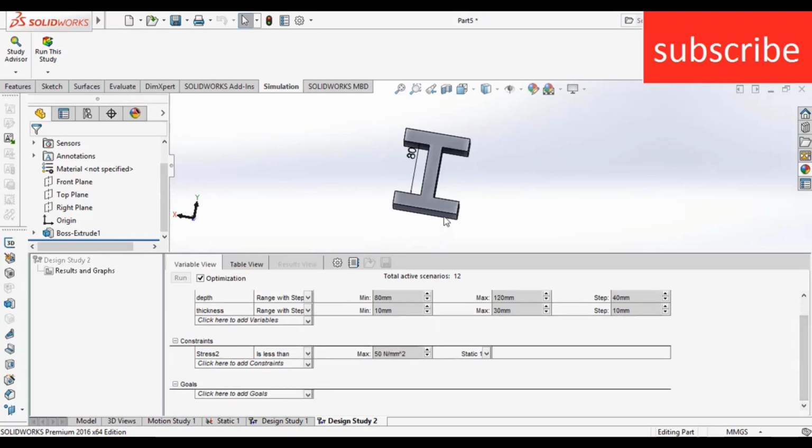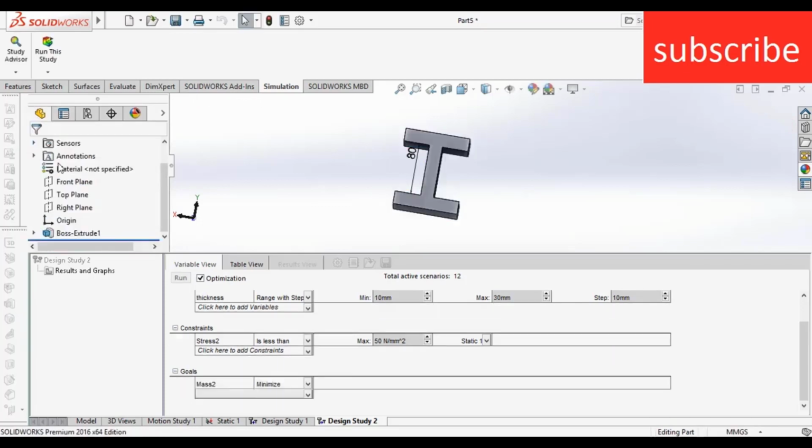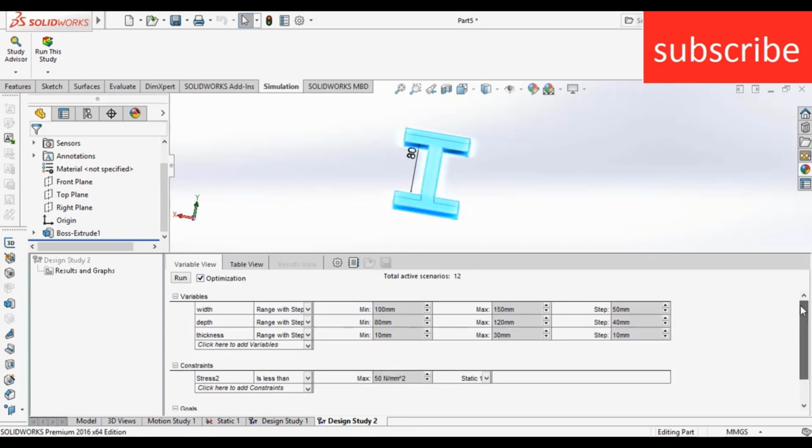So it will run this simulation and see where I get a maximum stress of 50 Newton per mm square with less weight. Now click on add sensor, click on mass properties, select this I-beam, click OK. Here our goal is to minimize the mass. If you want to maximize the mass, just click here and click maximize, and it will do the maximization. Now remember, we have set 100, 150 and 50 mm. Now I am going to run this simulation and you will realize what this does.